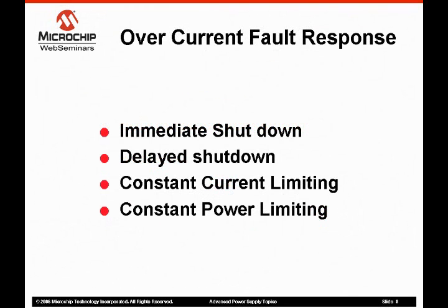There are four basic behaviors a power supply can provide in response to an overcurrent situation. 1. The power supply can immediately shut down and then periodically check to see if power can be restored. This is the auto restart function. 2. The power supply can tolerate the overload for a period of time before it shuts down, perhaps a few minutes. This is thermally limited.